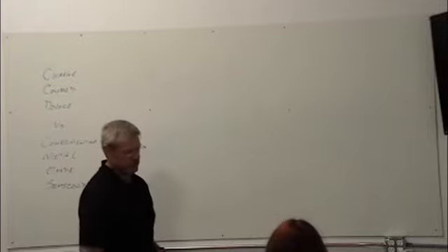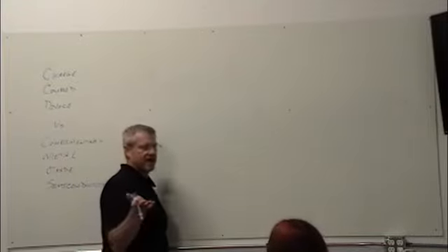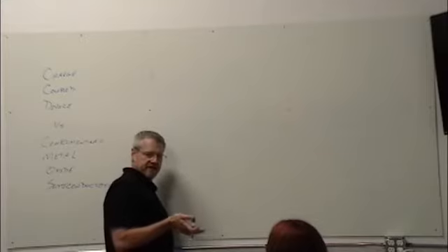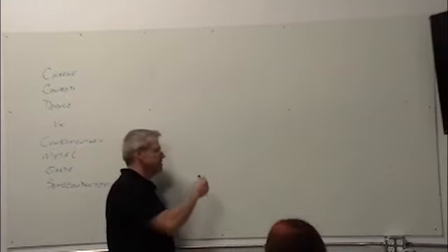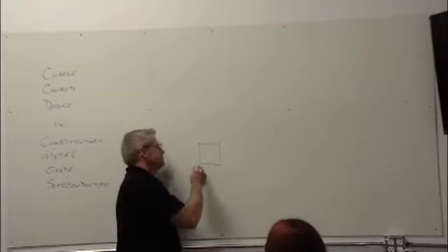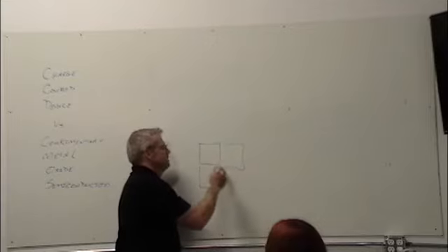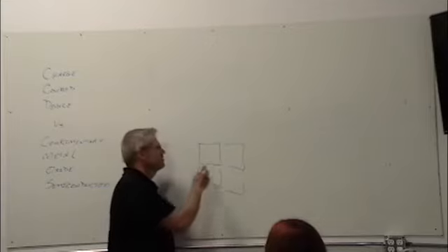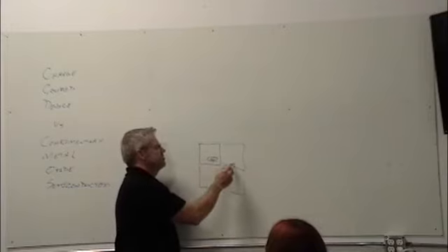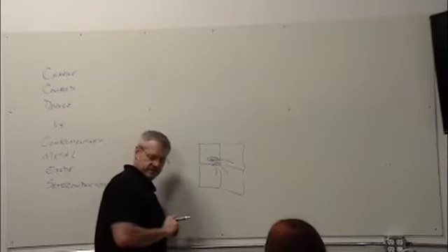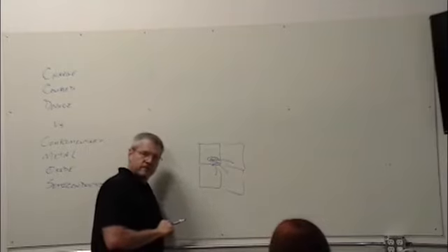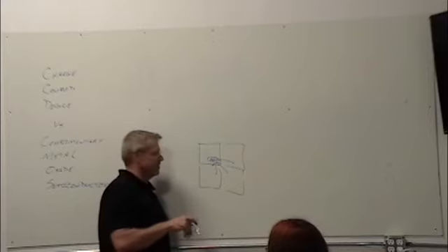And one of the other things you can do, so we're talking about CMOS, there's something called active CMOS arrays. An active CMOS array, which is part of what my thesis was about a bunch of years ago, is where, because you've got processing capability there, you can do processing of each one of these elements, and you can base it on the neighboring elements. Some filtering, Derivative of Gaussian and Laplacian of Gaussian, dogs and logs. Take that anywhere you want to go.